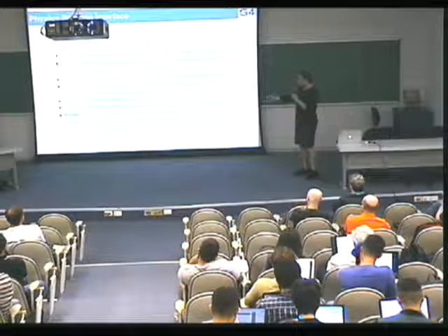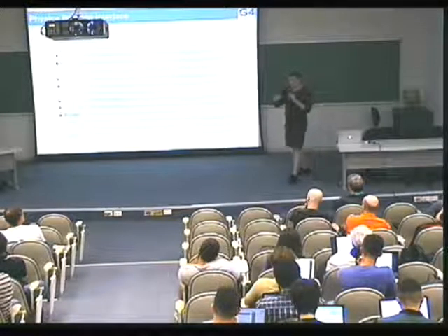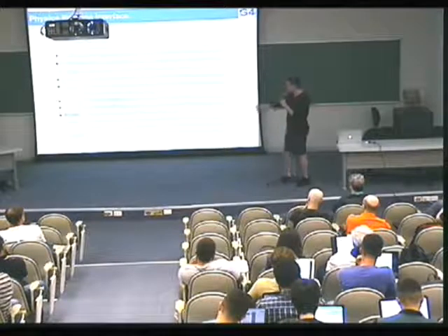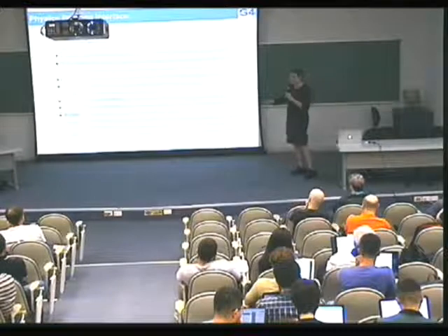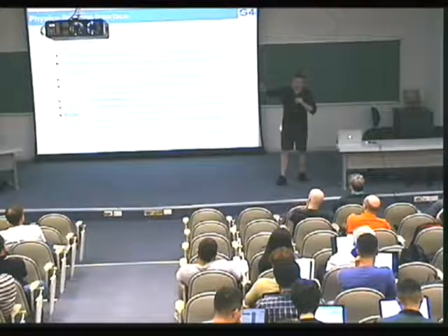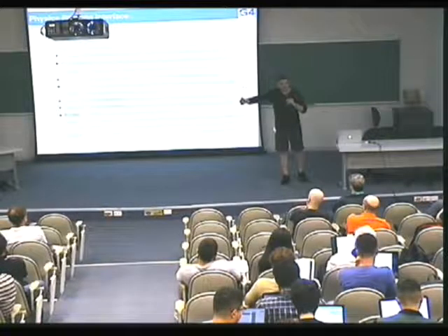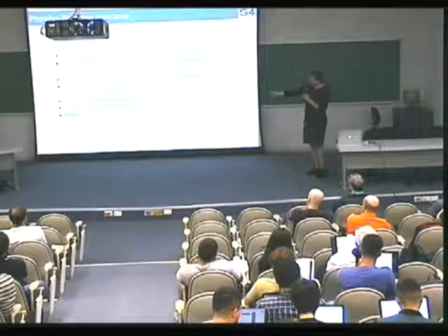For each type, the process needs to be able to tell how far the particle goes until the next post-step interaction happens, and what happens if the post-step interaction really happens. Similarly, how far the particle goes until the along-step interaction lets it go, and what happens along this step. So each type has one GetPhysicalInteractionLength and one DoIt method.